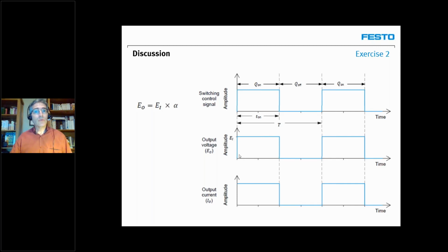And quickly enough will be multiple thousand times a second. So I can turn my transistor on and off 1,000 times, 10,000 times, 20,000 times a second. The resistor will warm up anyway, because there will be a constant flow of electrons through it. Even if it's on and off at that frequency, it will not see the difference.